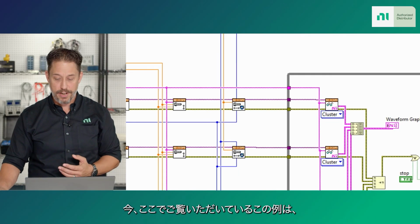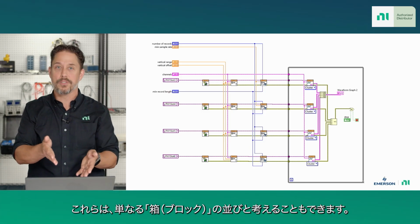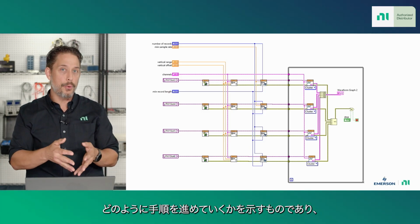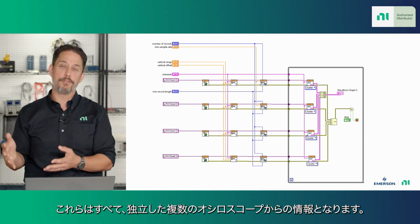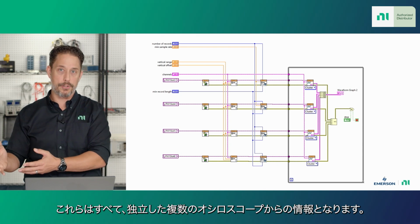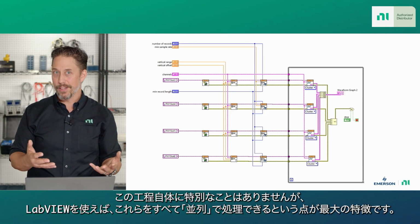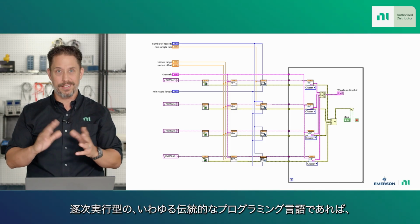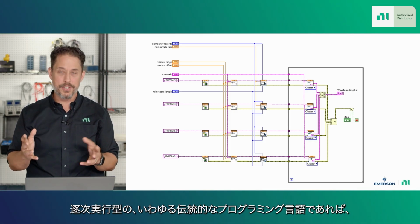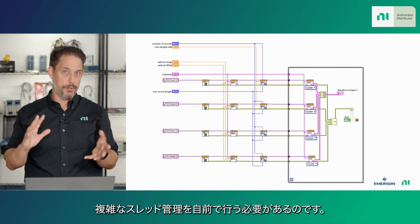Now, the example that we're staring at here is what it would look like in any situation. This could just be boxes as well, as to how you would go through, configure in parallel, and fetch in parallel all of the information from multiple separate oscilloscopes. There's nothing unique about this except that LabVIEW is allowing you to do it in parallel. Keep in mind, if you were trying to do this with multiple oscilloscopes in a sequential or traditional programming language, you'd have to do all of this sequentially or do all of your parallel threading just to be able to do all of this in parallel.